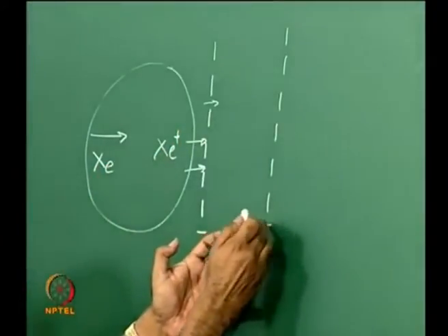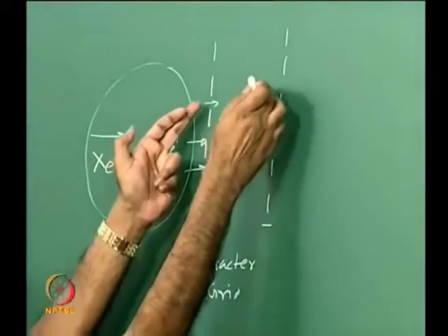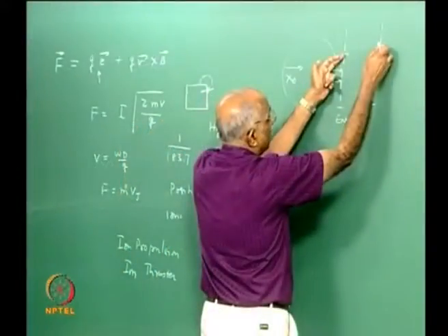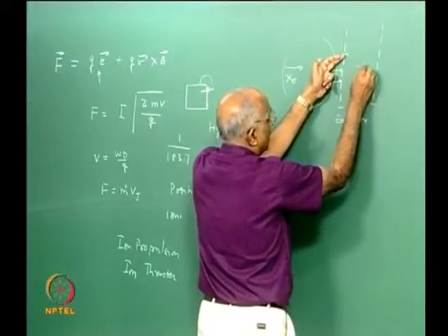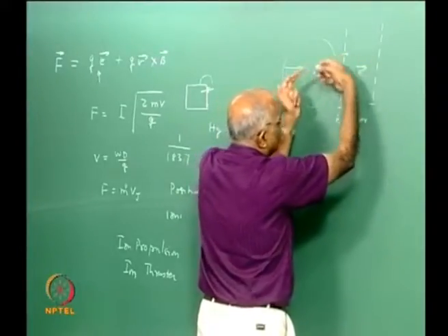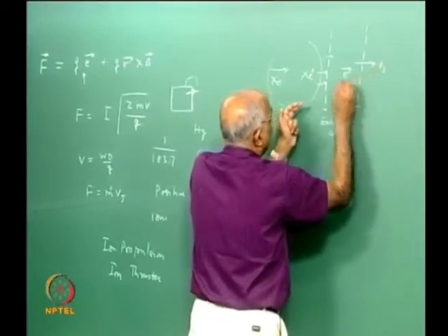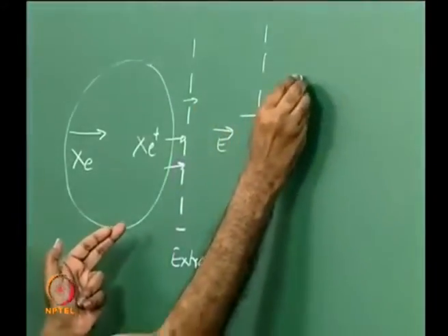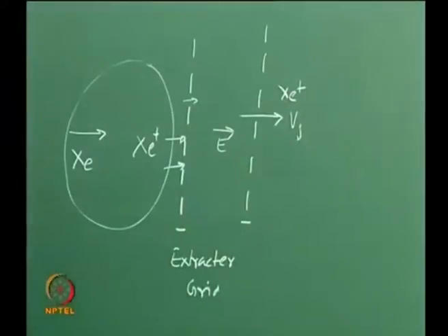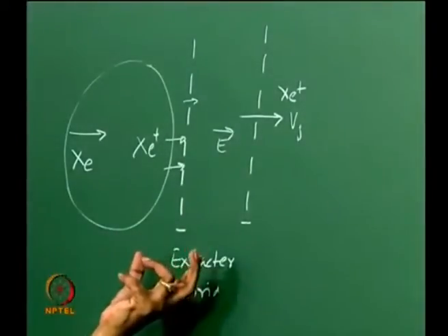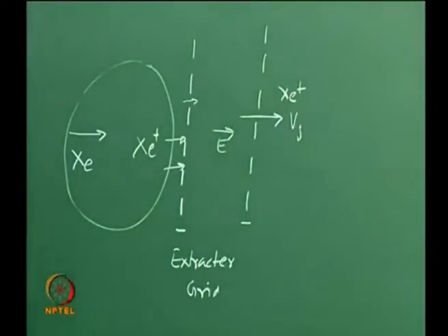This is still more negative, and therefore what happens is, because I have some negative space here, or rather I have a field here, an electrical field between this and this, it is pulled here and it is accelerated, and out go the ions, that is xenon ions, at a high velocity Vj, and therefore this will be the construction of an ion rocket or ion thruster.